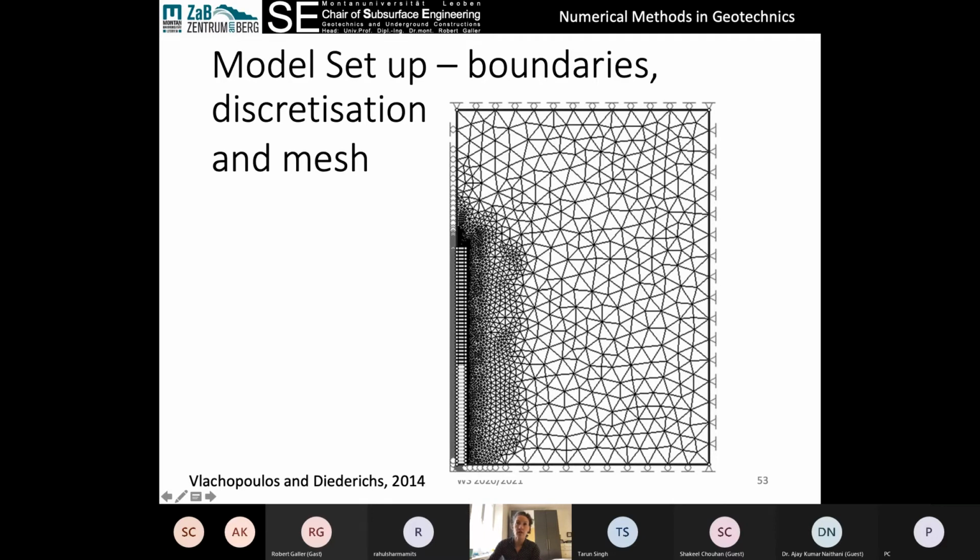But closer to our excavation boundary, we're actually really interested in what's happening here, often at the millimeter scale. So our elements need to be small enough to capture those small amounts of deformations and to have a good precision for the changes in those deformations with space.